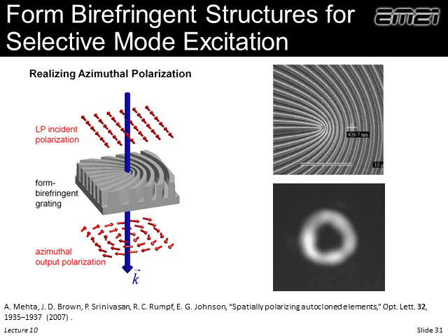So there's a very good reason for doing this. Some folks, and in the past we worked on this, were interested in exciting a metallic waveguide. And it turns out if the electric field is polarized perpendicular to a metal, boundary conditions say there can be an electric field inside that metal. We induce surface currents and there's a lot of loss. The boundary conditions for an electric field polarized parallel to the metal say that the field has to be zero at the metal. Well, if the field is zero at the metal, there's really not a whole lot of interaction there. We're not inducing currents, and in fact, that's a much lower loss beam.